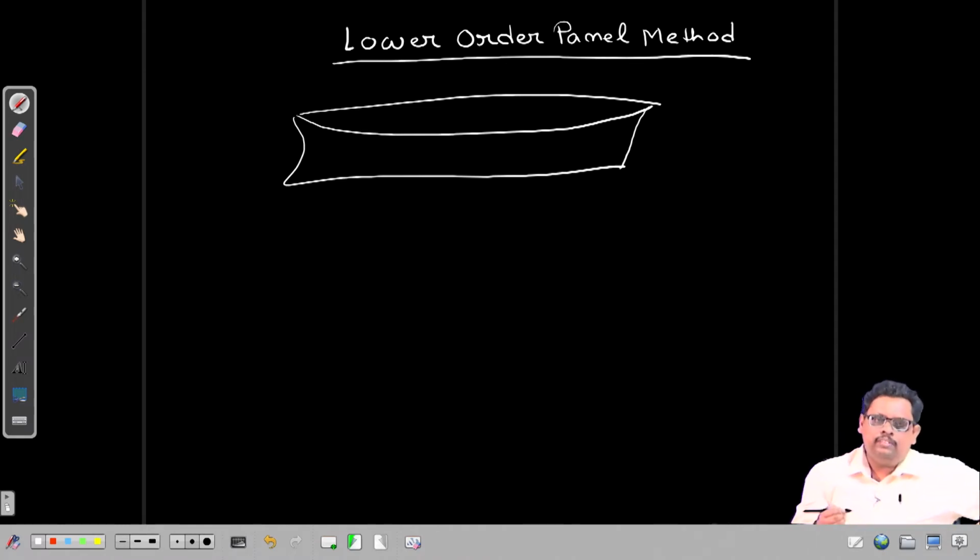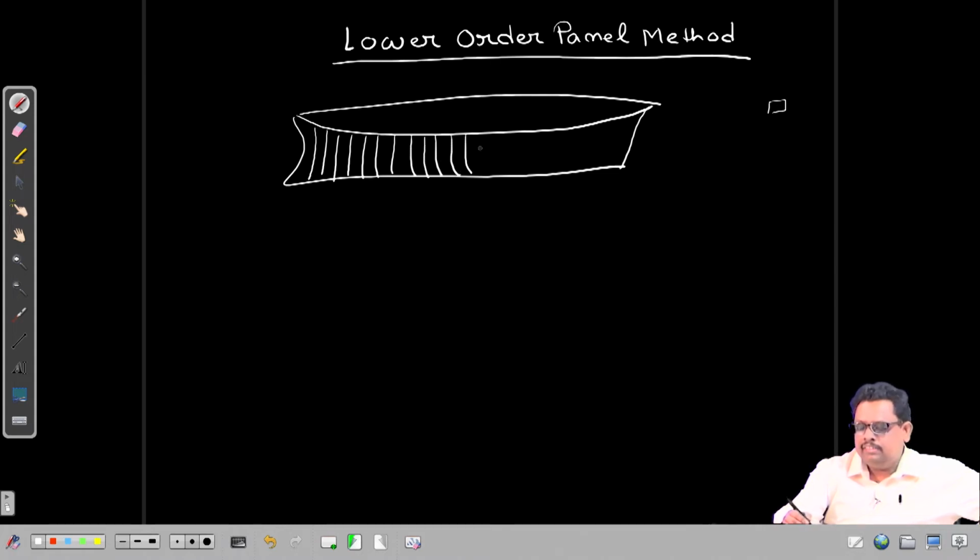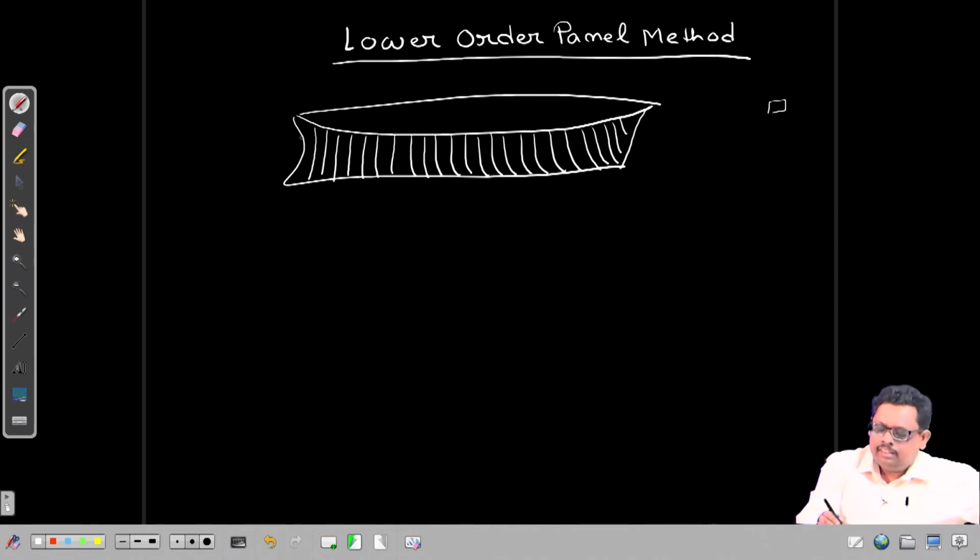So, we cannot say it should typically be a rectangle. It is not possible, because you can see this part, you really can't do some rectangular stuff. So maybe you have to do something else. Now, even if I discretize this way with some sectional lines, as I mentioned, I can draw some section lines. Since it is symmetric, you can mesh only one part and define that it is symmetric. The other part one can automatically take care of, and this is the water line.